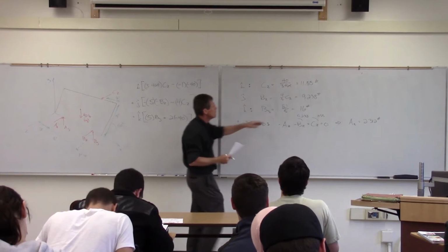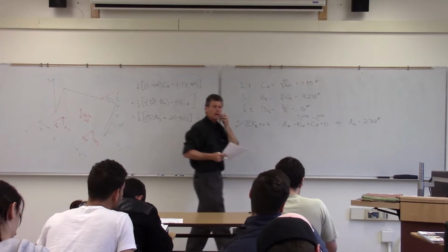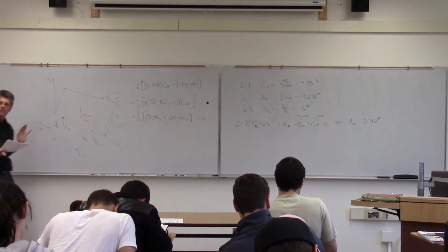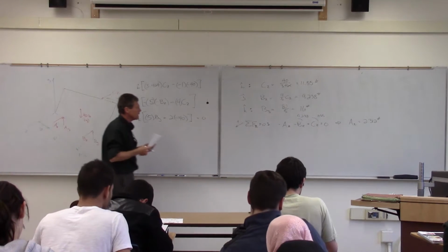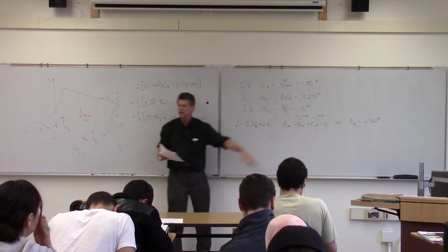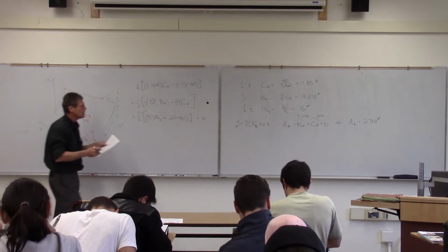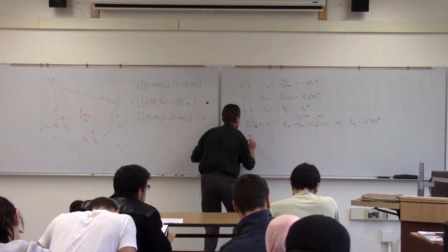Oh yeah, we got BZ. So we got BZ at 9.2, and then the AZ is 2. And that's because of the unsymmetric set of supports that we have there. But again, be careful, make sure that when you're doing this sum of forces that you pick up all of the pieces. And then the final piece is sum of forces in the y direction.